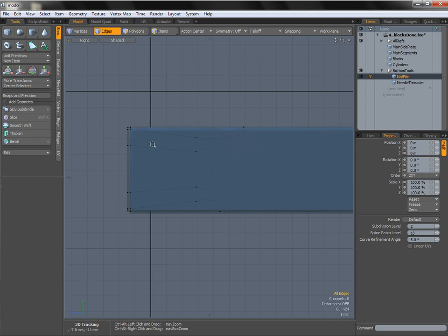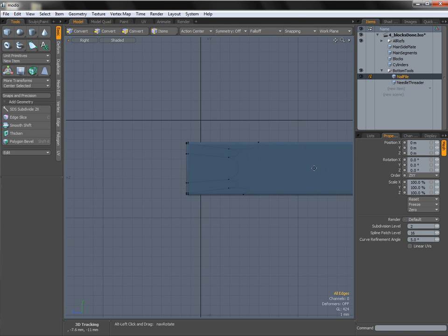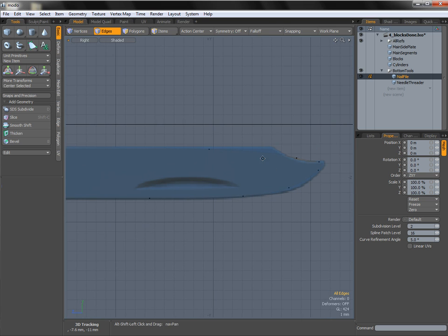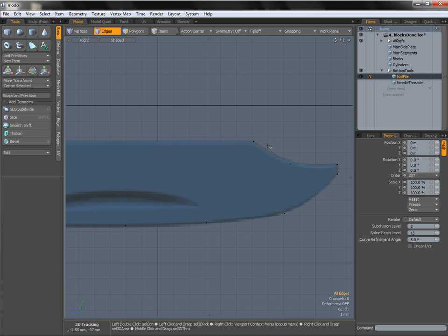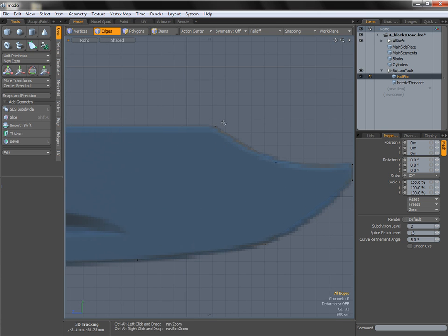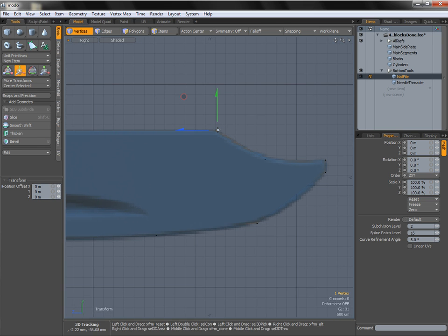The corners on this left-hand side of the nail file, we're going to go and take a look at the other sharp corners that we've lost when converting into subdivision surfaces mode. First of all, we're going to come along the top edge and take a look at this one. If I go out of subdivision surface mode by hitting the Tab key, you'll see we've got this single vertex here that is sitting on this corner on our reference image. And what we want to do is make that vert sit roughly there when we go into subdivision surface mode.